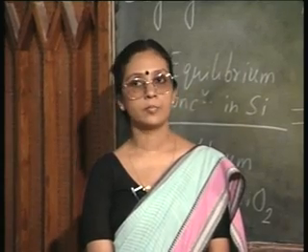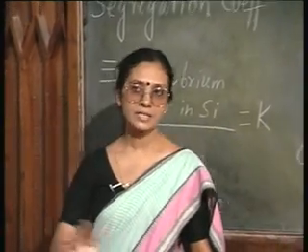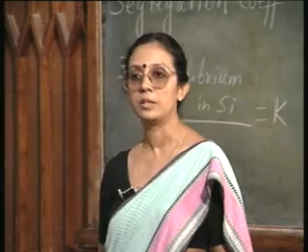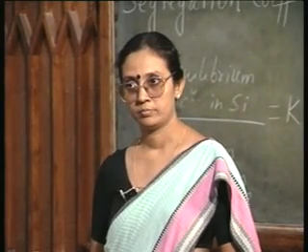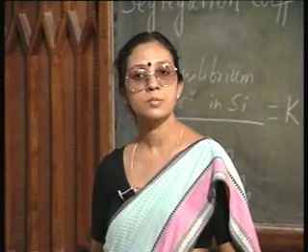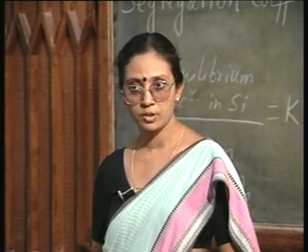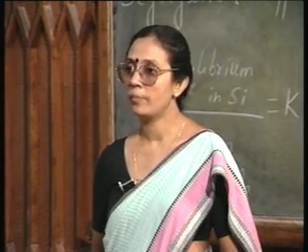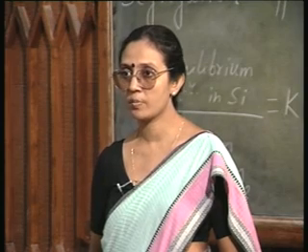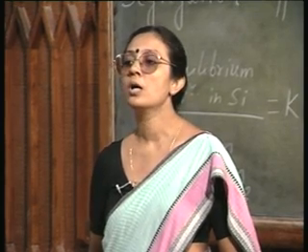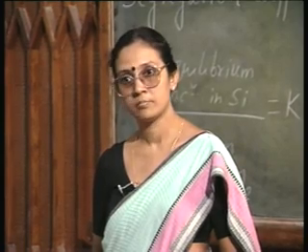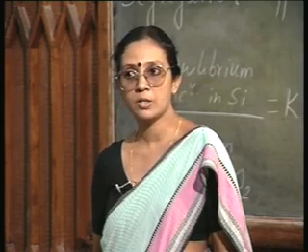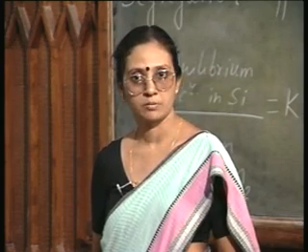So, this is something which is done. It has a number of interesting fallouts. First of all, your problem of growing thicker oxide is now solved, right. You have increased both the linear and the parabolic rate constants. Therefore, at the same temperature and in comparable time compared to the atmospheric pressure oxidation, you can now grow a much thicker oxide without the fear of devitrification, because you are not subjecting it for any longer duration or at any higher temperature.